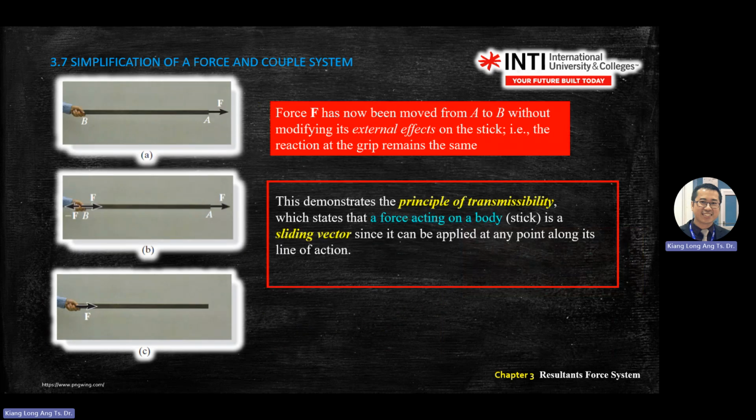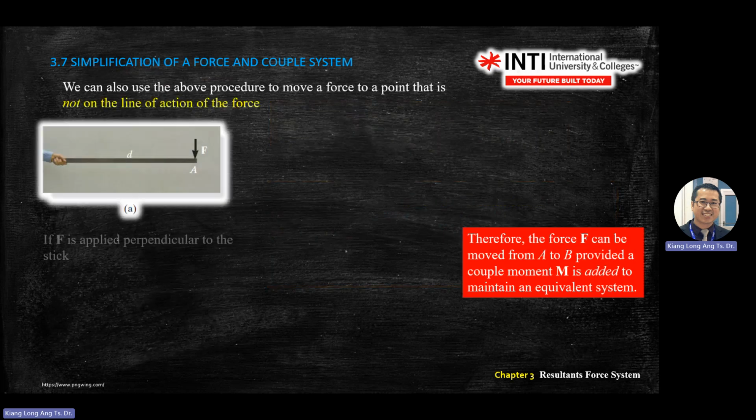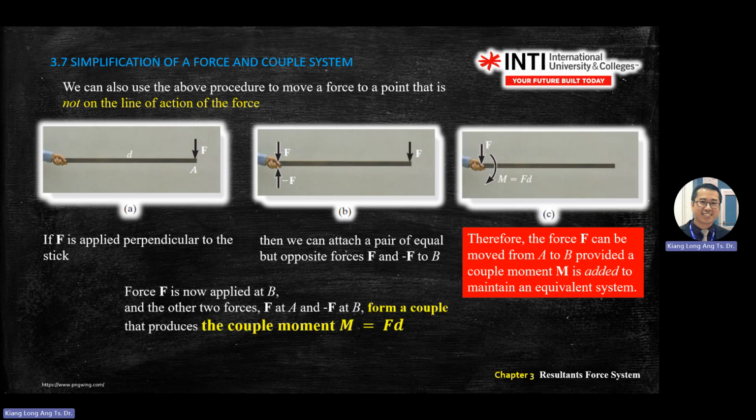One is this diagram. If you change the location along the axis, it doesn't matter. You just pull the full magnitude forces along the axis and put any location you like. However, when you do modification on the perpendicular forces to the axis line, remember you are changing forces. Your result will get forces plus the moment at the other end of the point that you move.